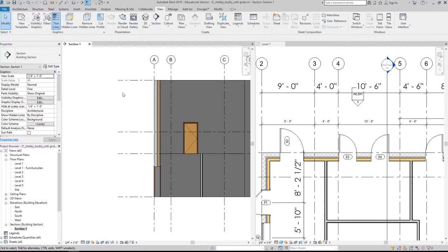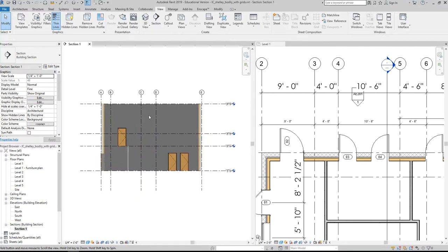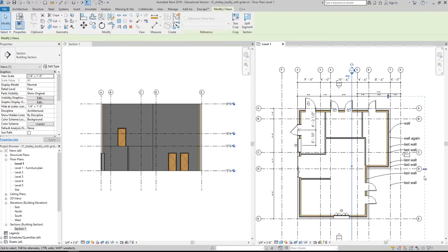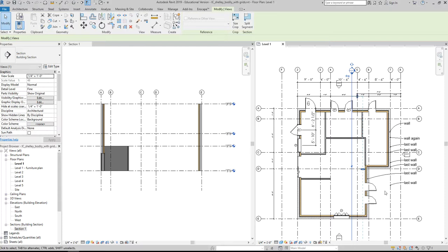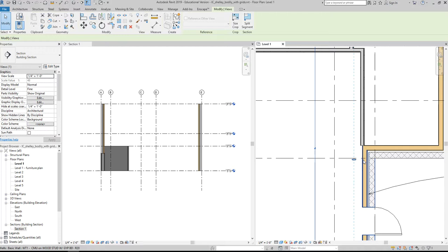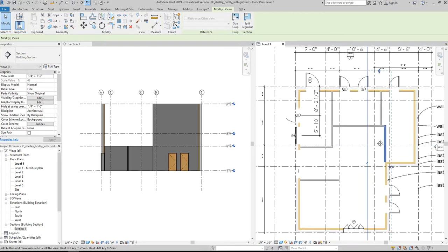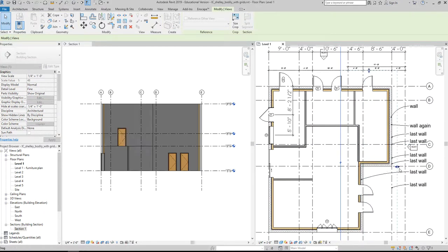Now I'm going to use WT, window tile, so I can see them at the same time. And I'm going to show you what happens when I move my section or I change the extent of the view range, right? So I can drag this in. Watch my building section change, right? Because I'm cutting through here, but I'm not quite engaging this back wall, so I can't quite see it. You see my back wall starts to show back up, but nothing is showing beyond there, right? So Revit is very good at real-time indicating what we're able to see.